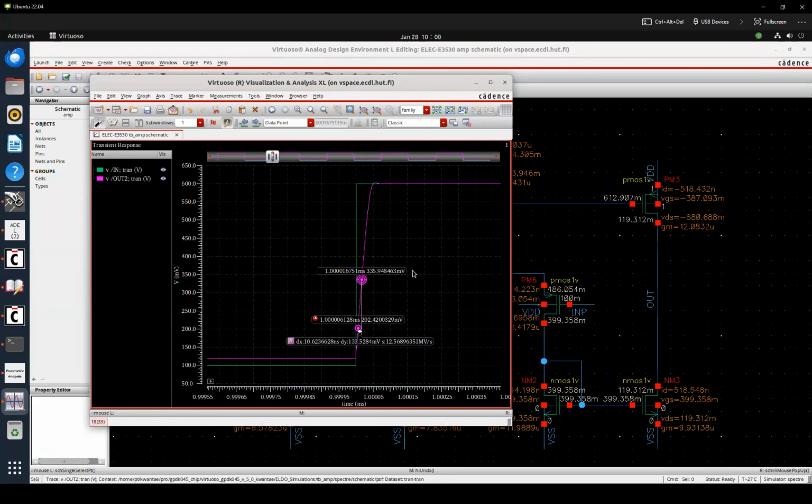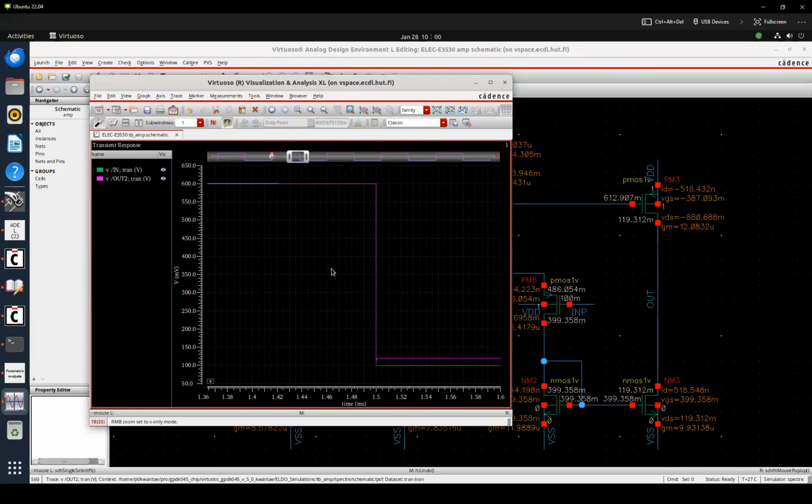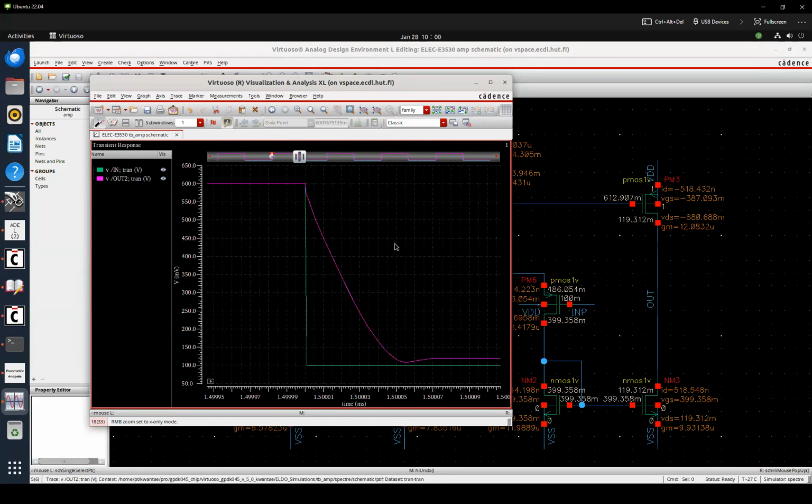And similarly, you can also measure the falling edge slew rate like this. So it has a slope limit because this edge is too sharp. So this curve cannot go fast enough to follow up this sharp edge. That is what happens when you study about the slew rate of the amplifier. So it goes to almost the same, like 12 volts per microsecond.